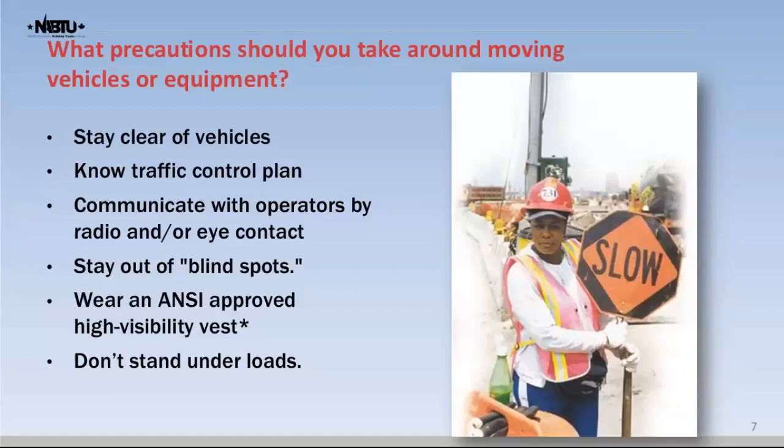You also want to wear ANSI-approved high-visibility vests. You can see in this picture, this worker is wearing a high-visibility vest. Okay, so it's a bright red color. It has some reflective material there. You can see that if it's in the evening, that reflective material will definitely show up and make it so that worker is seen.